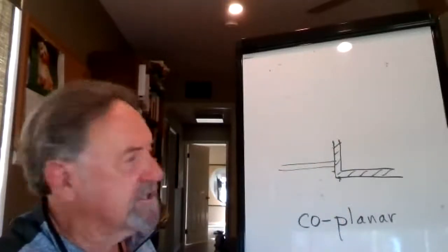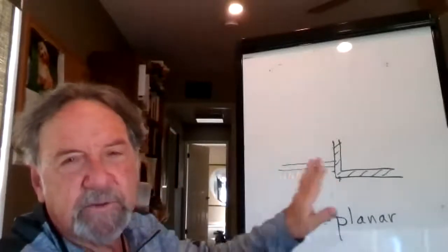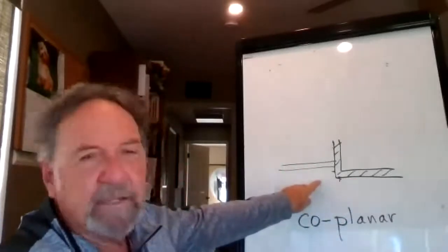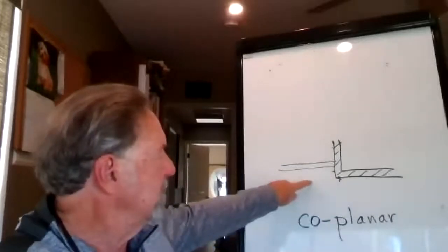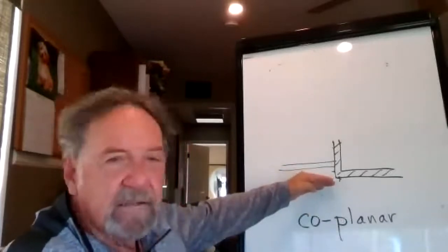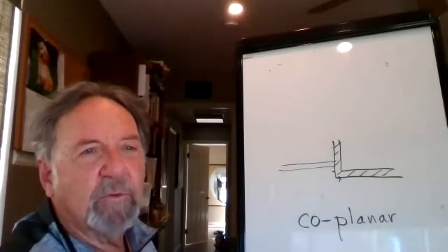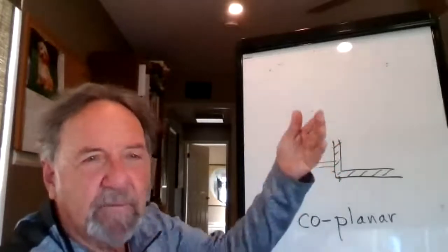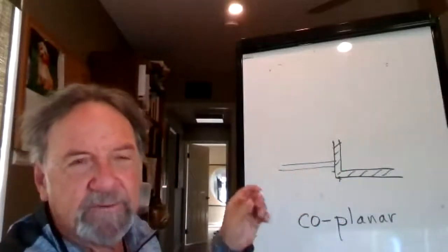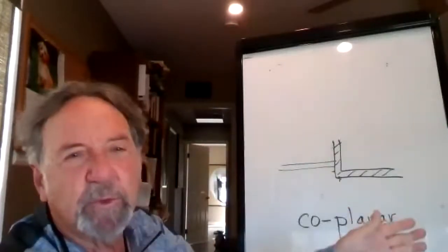The other thing you can do is either shift it or keep it coplanar, but use a different covering material. So if this is stucco, you might start this wall. If it's coplanar, you could put siding there and have the siding stop where the old stucco is. And that way, you see that all the time, alternating stucco and wood. It's a great way to not have to worry about that joint.